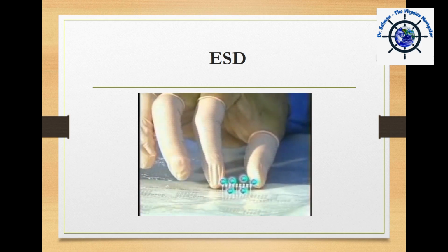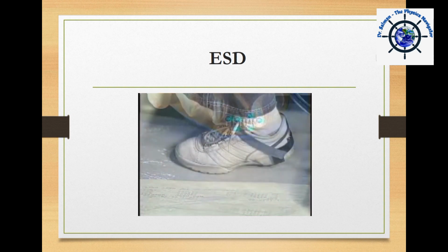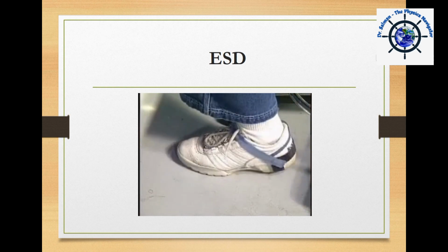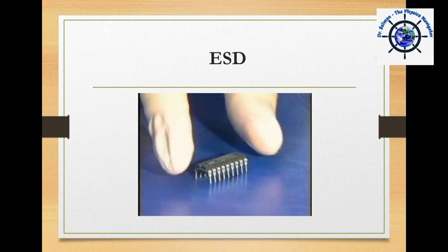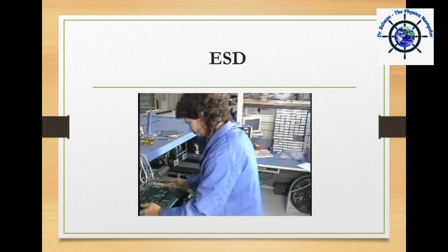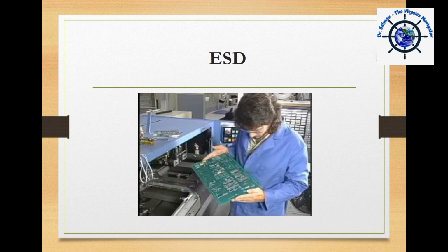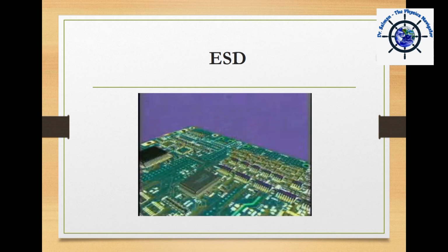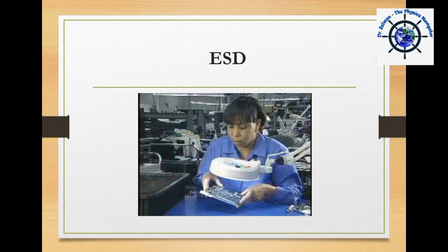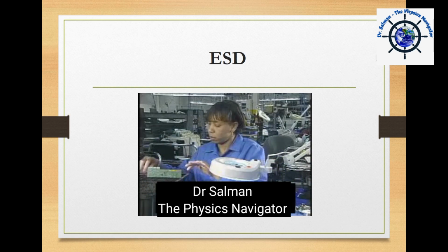Don't slide the device over any surface. Sliding can also generate static charges. And avoid any extra movements when handling the device. Again, this repeated touching and separating can generate charges. When handling electronic assemblies, it's important to hold them only by the edges, minimizing contact with any conductive surface. Because components are connected, an ESD charge to one component can easily spread to others. The key point for handling is to minimize handling of ESD-sensitive items as much as possible.